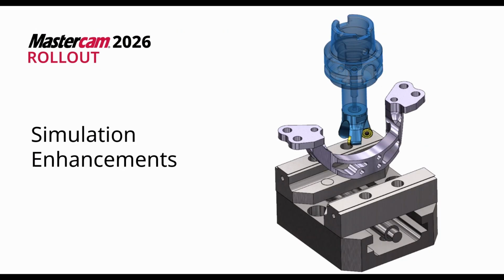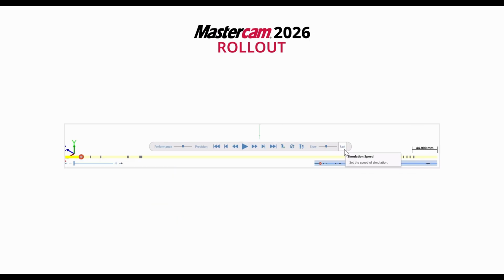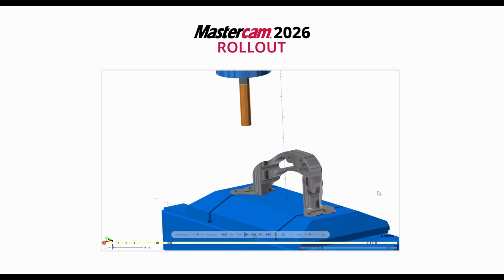There's also a few simulation enhancements in Mastercam 2026. In the move info, there's a new operation info section that gives you some information about your operation. There's also now a fast and slow button added to the play ribbon bar that increases and decreases the speed by 10%. And there's a new graphics option to display material texture, similar to the material options in the standard Mastercam window.